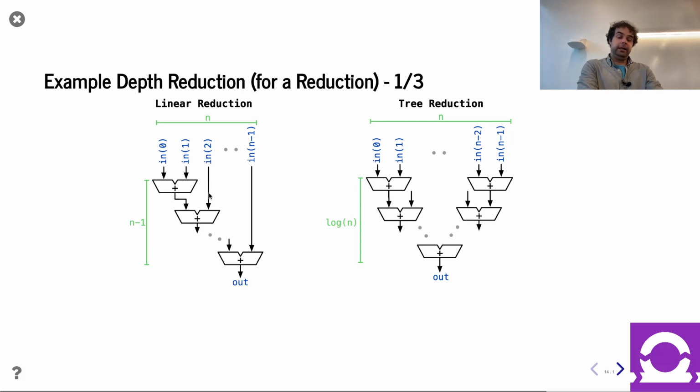Good question. Sort of, but it's not going to give you quite what you think. In Chisel, the question was, there is an ability to have growing additions, so there's no chance of overflow. We can work this out ourselves. Let's say originally these are k bits; I would say n, but n is already used. You add two k-bit numbers with no chance of overflow, and you get a k plus 1 bit result. A k plus 1 bit thing plus a k-bit thing, to be pessimistically conservative, needs k plus 2 bits. So after this chain, you need k plus n minus 1 bits in your adder.